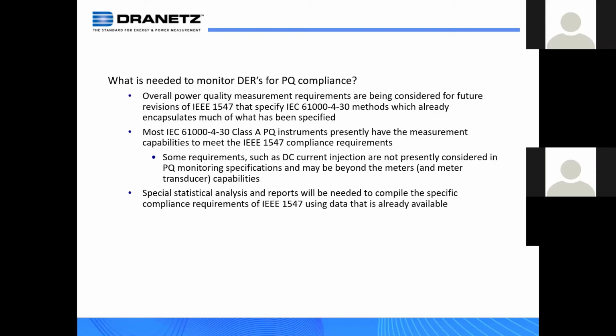So the utility makes the decision to take a system offline. Well, maybe something needs to validate that that was a true decision. You know, maybe there were power quality problems or harmonic issues, and the utility shut off a DER as a result of that. We know that happens today, but it's just not automatic. We've been involved in wind farms where the utility wants to shut off the wind farm because it's generating too many harmonics. There's an issue with it. Okay, so there's definitely a future in the monitoring of this.